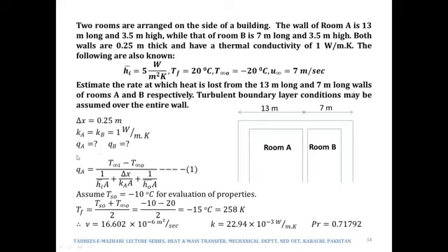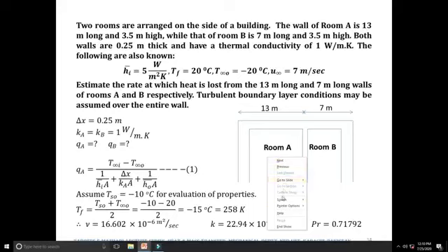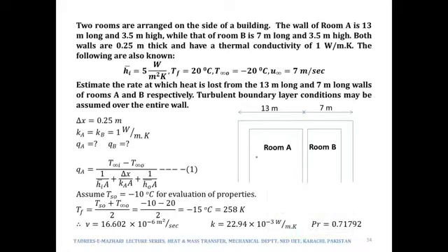Now if we use this simple expression, because we know the temperature inside the room, which is plus 20 degrees Celsius, and we know the temperature outside, which is minus 20 degrees Celsius, and in between there are of course three resistances.